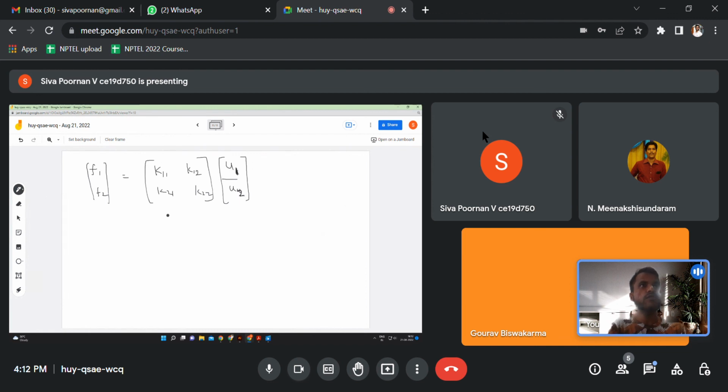Now what we are saying is that f1 is k11 times u1 plus k12 times u2. Now we know that u1 is going to be 0. Why? Because we can always make the zeros come on top. That is possible, therefore I'm able to write it like this. Therefore this is going to be 0. So f1 is going to be k12 times u2.